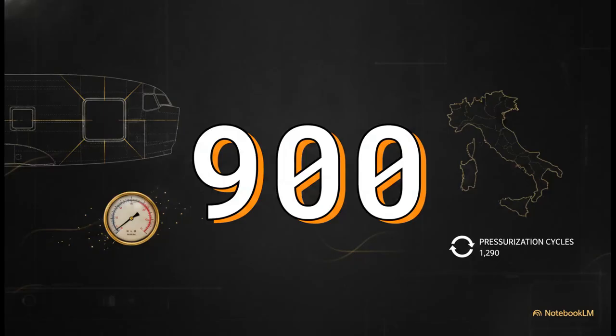And then, just months later in April 1954, an identical tragedy struck. Another Comet suffered an in-flight breakup near Naples, Italy, also while climbing through completely routine weather. And this aircraft had completed even fewer flights, approximately 900 pressurization cycles. Both of these numbers, 1,290 and 900, were shockingly far below what earlier factory tests suggested the fuselage could safely survive. So the entire Comet fleet was immediately grounded, and investigators launched one of the most extensive forensic engineering efforts in history.